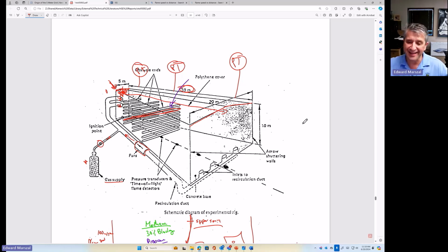Based on that, that gives you a background into the 5-meter grid. That gives you a background into what size of gas cloud I should be picking for my critical gas cloud in a geographic risk study. It gives you some information on where you might want to use different numbers and some resources to match what you're doing versus what some of the tests have been done in industry.